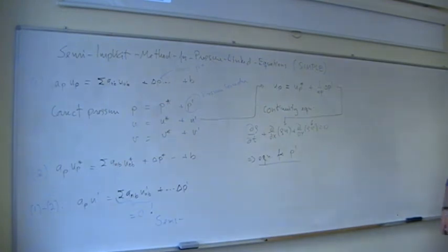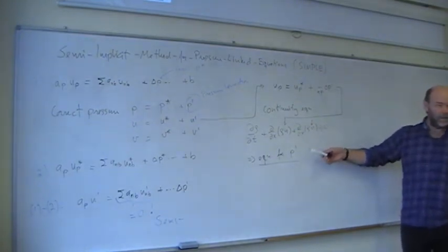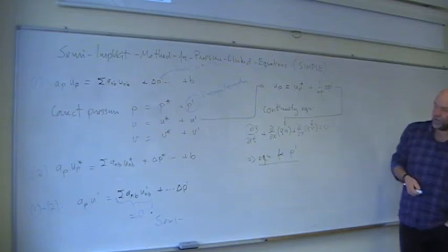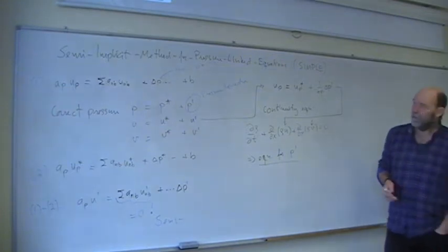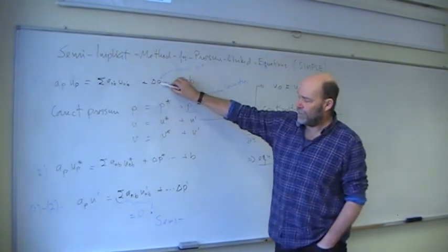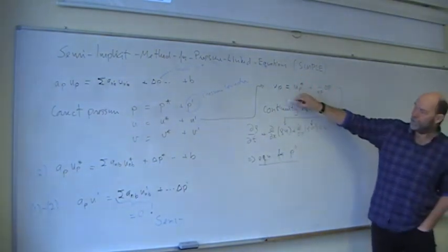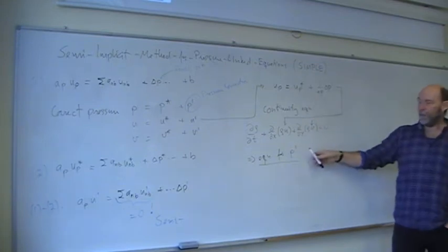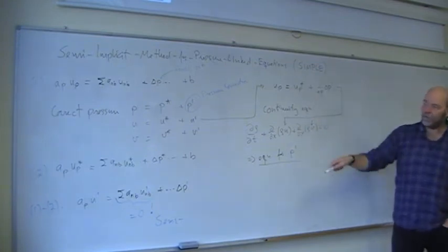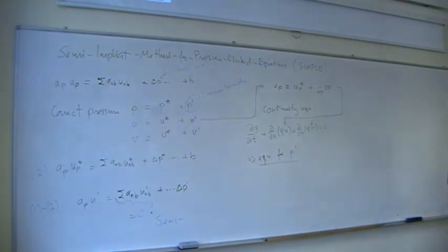So you use the continuity equation to find an expression for the correct pressure adjustments, and then you insert and you guess again, and you do it again, finding new better velocities to be inserted here, finding a better correction, and so you continue. So this will be the recipe for SIMPLE, the classical SIMPLE.